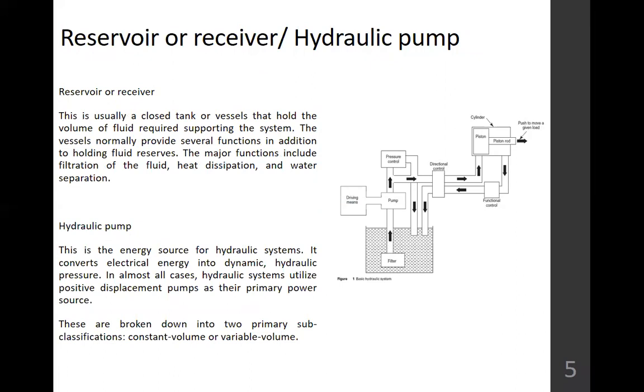For receiver or reservoir, this is usually a closed tank or vessel that holds the volume of fluid required to support the system. The vessel normally provides several functions in addition to holding fluid reserve. The major functions include filtration of the fluid, heat dissipation, and water separation.